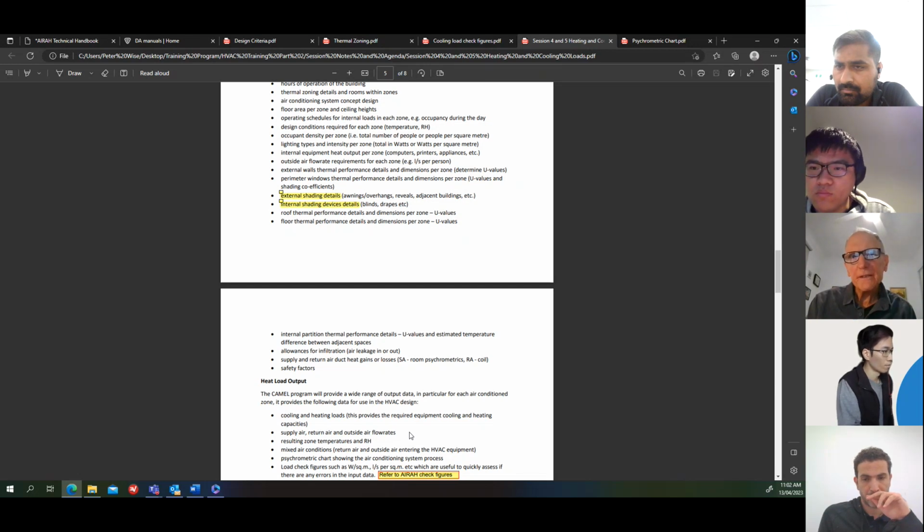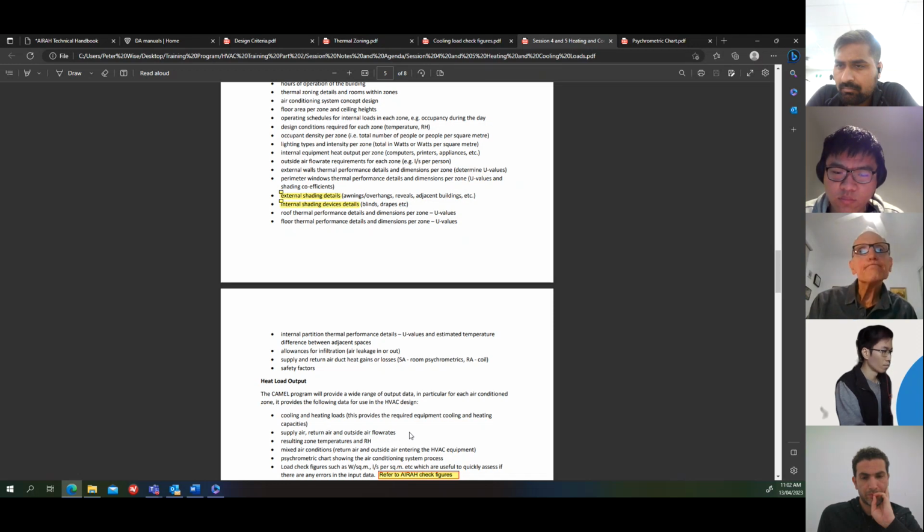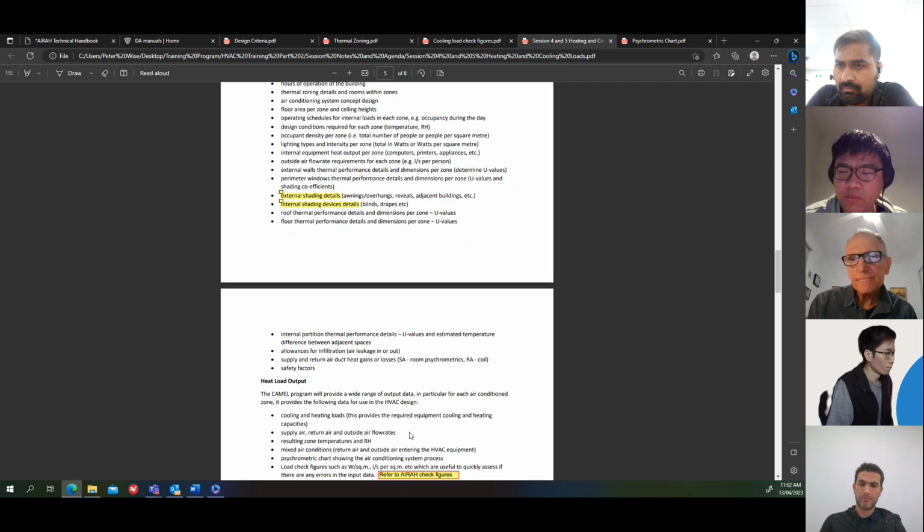Again, this is like another safety factor, because if the building is pressurized, you may have almost no infiltration at all. If it's a modern building that's got good sealing, and it's a requirement of building practices these days to seal buildings very well, and if we talk about an office building, the outside air is greater than the exhaust. So you've got positive pressure in the space, which is going to prevent leakage anyway. So by putting in infiltration, it's another safety factor.